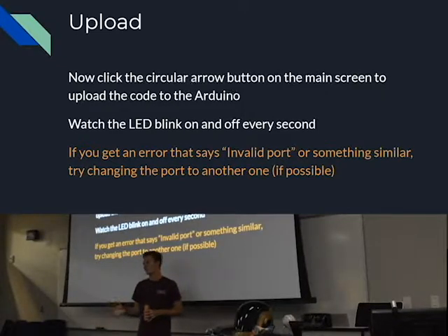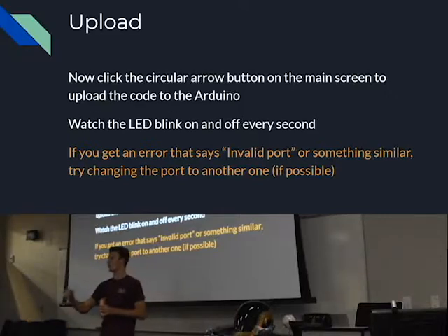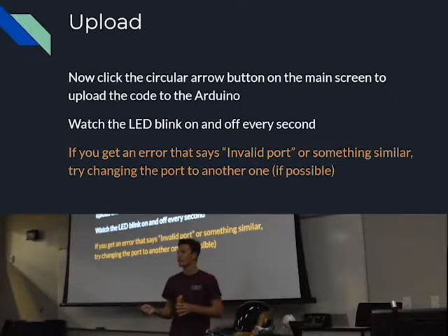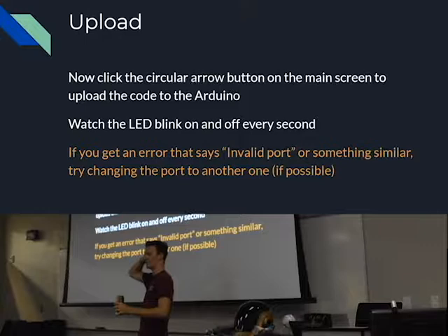It's just the name of the function. So it's like, hey, turn on LED_BUILTIN, and it says HIGH. That means I'm going to turn it on. I'm going to turn it to a 1, whatever you want to call it. And then there's delay of 1000. Now Arduino measures things in milliseconds, so that's 1 second.